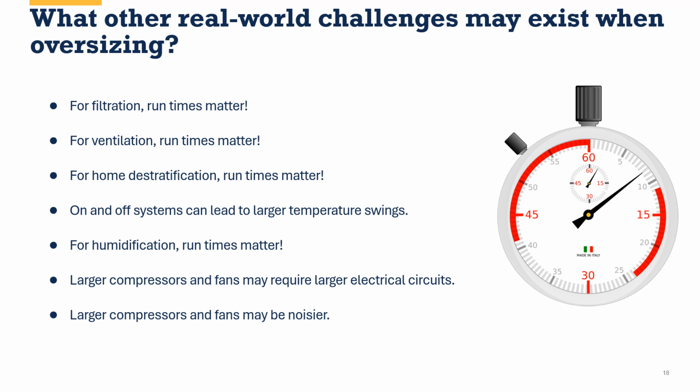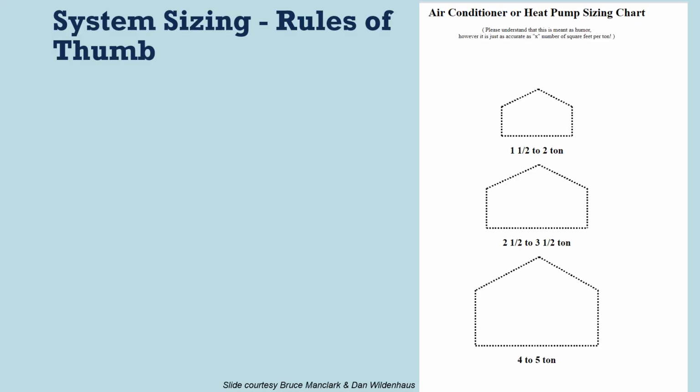Larger compressors can be noisier. Let's go for the smaller compressor with long, consistent run times. That will hopefully lower our noise the most. And then again, I keep mentioning this because it's so important. These oversized systems can struggle with the existing ductwork. It is an important part. We will get into this more in the second of these 2 recorded seminars.